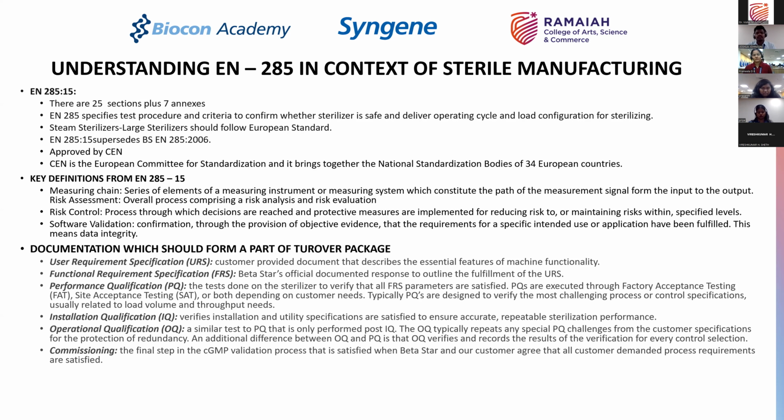The last activity which is done is a performance qualification, where you take the actual load. So I'm going to charge in the garments, I'm going to do liquids, I'm going to do XYZ. So you decide your load patterns, you put them inside the autoclave and run performance tests, so that you are assured that sterility is being met. And this time you put in all biological indicators at different locations, plate them out, so that you are sure that your cycle is properly working.